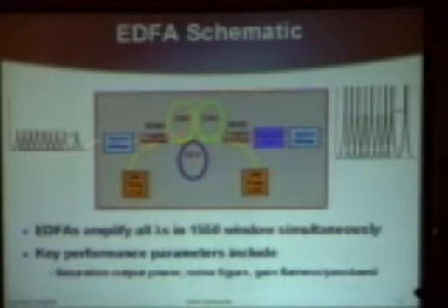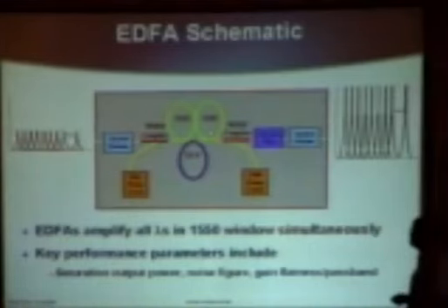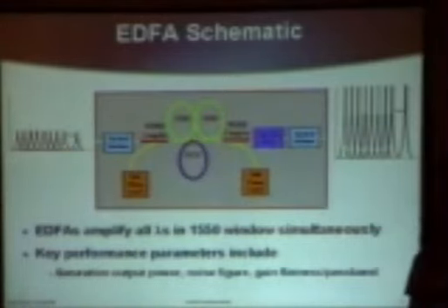There's a special fiber, the erbium doped fiber, hence the erbium doped fiber amplifier, that has an erbium atom added to it, and without getting into the physics, if you pump it with light, the erbium atoms get excited, and when the signal goes through, they amplify the signal spontaneously. They give the amplification of the signal. So we have a very simple device now that is bit rate independent, and as long as your wavelengths are within the passband of the EDFA, it's channel count independent to a great extent too.